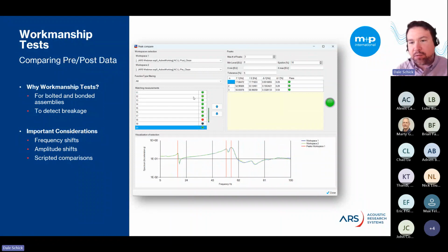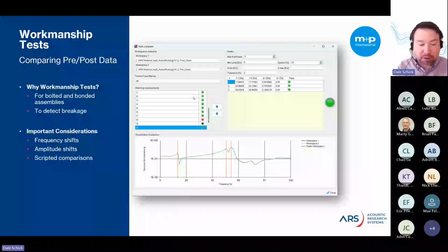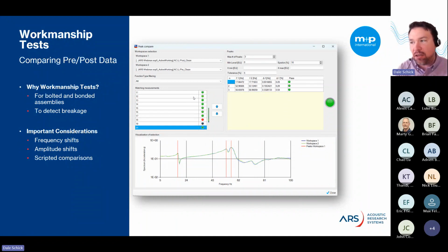And I talk about workmanship a little bit here because for some testing campaigns, especially if you're a startup and you're making a new type of spacecraft, or maybe you're a college or university and funding is scarce, there have been situations where the launch vehicle manufacturer was able to waive vibration testing in lieu of acoustic testing. So as long as the acoustic test was met without any compromises based on their specification, you can do some analysis work to try to call that acceptable for launch.